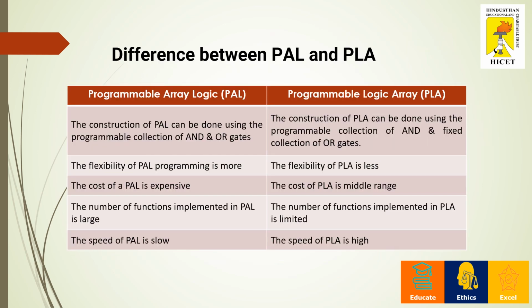We will have a quick review of the difference between these two, PAL and PLA. The construction can be done with the collection of AND gates and OR gates in case of programmable array logic, whereas in case of PLA, it can be done by a collection of AND gates, but here the OR gates are fixed. PAL is more flexible to make your programs when compared to PLA. In PLA, the flexibility is comparatively less.